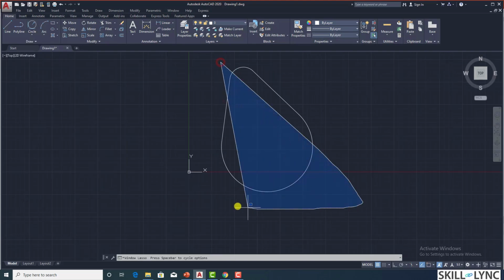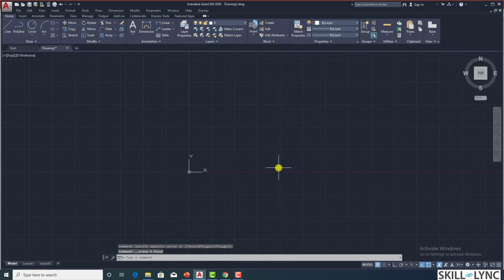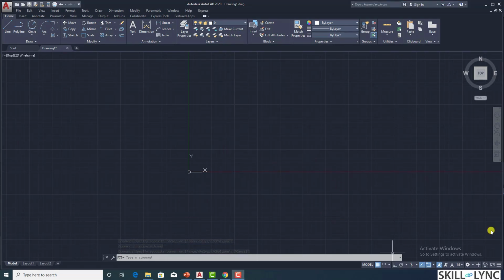So let us remove all. So for this tangent, there's no direct command available. If you click on tan, this is what has been displayed. That is, it selects a 3p, and then there's again a tan2 command, but if you try and enter it, it will throw out an error. So let me simulate this to you. Creating a circle and then selecting 3p and then tan2, then it will show as an invalid point. Okay, but there's another command.